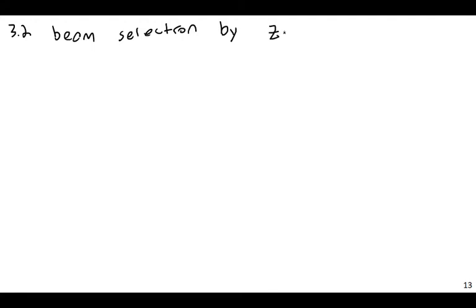Now, what's interesting about ZX is that this is your plastic section modulus. So again, this is a section property independent of material. However, we do know that ZX loosely corresponds to bending capacity. Not directly related, but you also need to consider buckling and material strength and things like that. But ZX is loosely proportional to bending capacity.